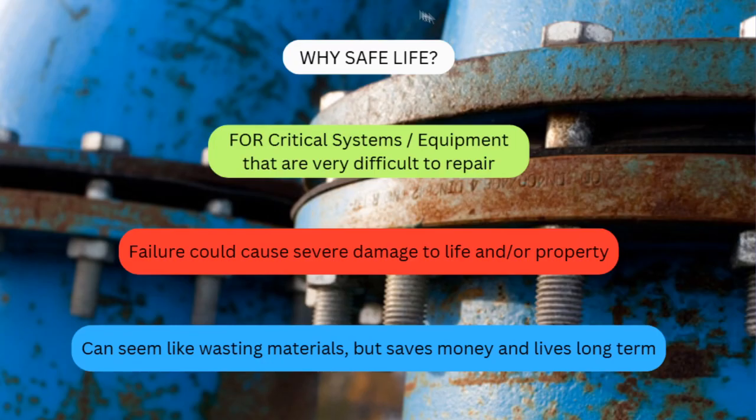So why would we have a safe life design philosophy? In oil and gas, there are so many systems at large scale that a lot of things can go wrong. At the same time, the cost to actually repair these equipments and the procedures to repair these equipments are very, very difficult and also very costly. So therefore, these equipments are designed to actually last a certain period of time in which the probability of them failing is very, very low. Then after this period of time, let's say 10 years, this equipment will just be automatically replaced instead of fixed.